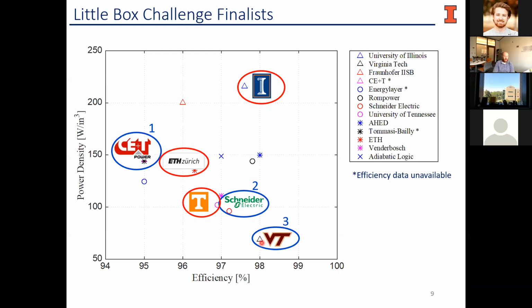And what that tells you is that only 3 of these power converters met all of those specifications when it came to ripple, when it came to EMI, when it came to the temperature rise and everything else here. So this is a great equalizer, right? We have this one box, everything kind of fits in there. We know how power density is being measured. It's just the power divided by the volume. We know that they're all meeting basically the same specifications. They might be exceeding the specifications, but they all at least work.